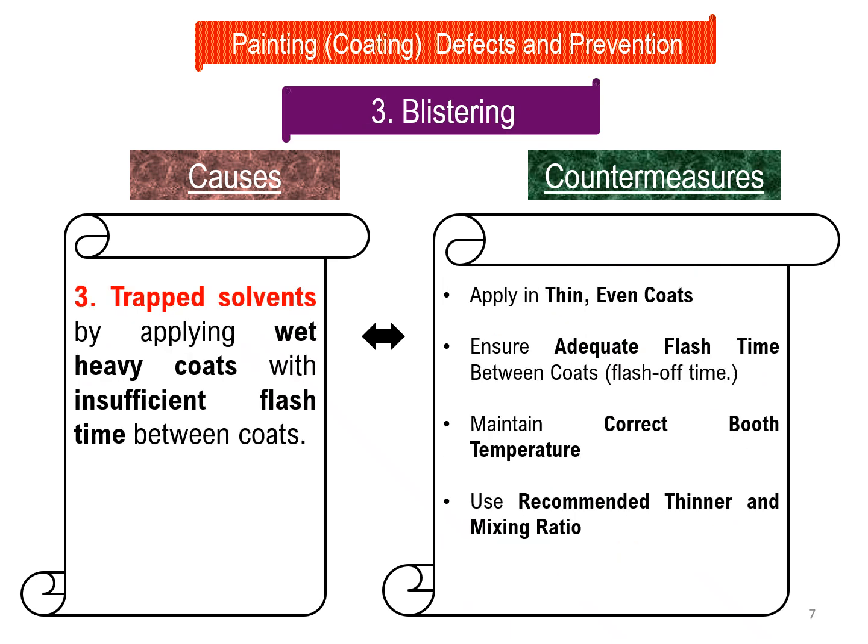Another important cause is probable trapped solvents by applying wet heavy coats with insufficient flash time between the coats. The recommended countermeasures are apply in thin, even coats, ensure adequate flash time, maintain correct booth temperature, use recommended thinner and mixing ratio.